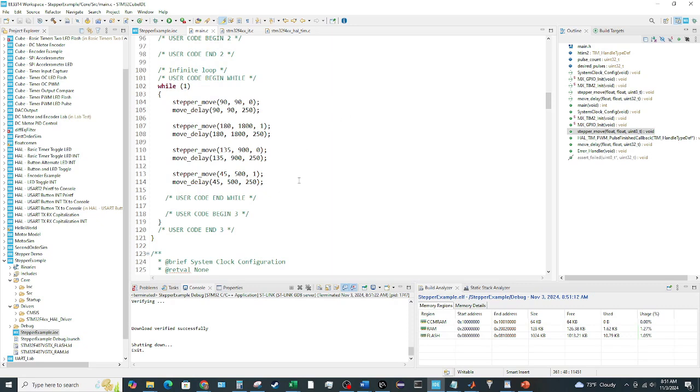So you kind of need to look at what your max speed is going to be. And that's where you need to adjust your prescaler so that you get an ARR value that's large enough to have a reasonable pulse value. Obviously at your highest speed, if your ARR is 1 or 2, that's going to be an issue. You need a little bit more resolution to give some sort of a pulse instead of just a constant high level.